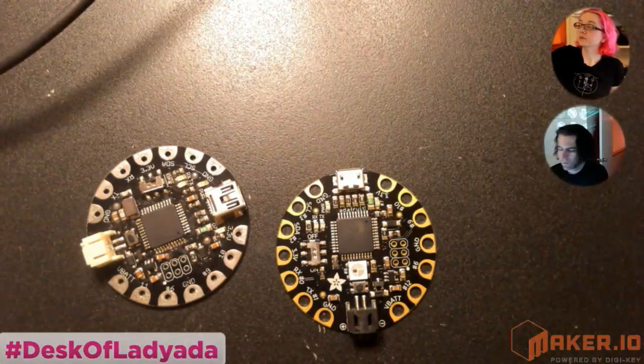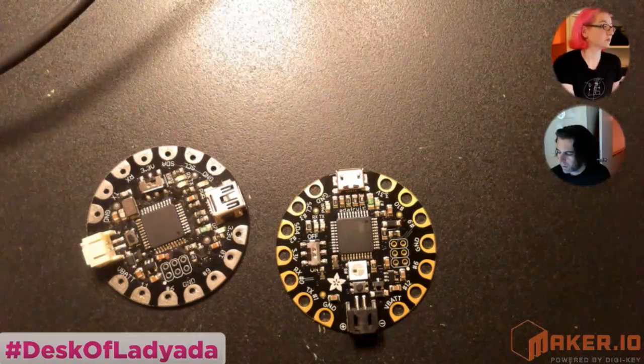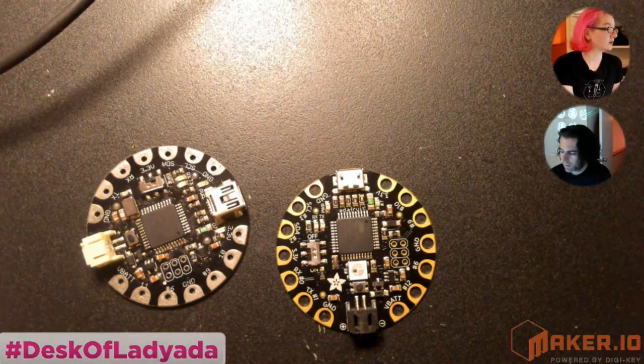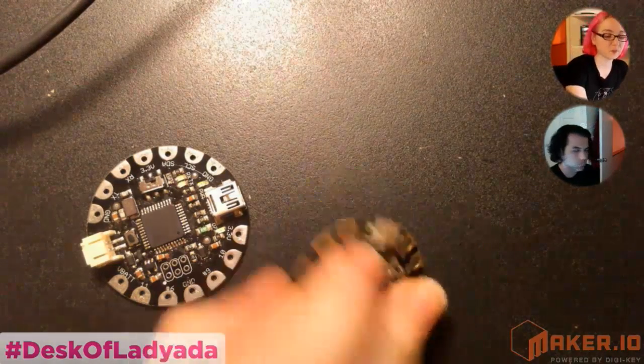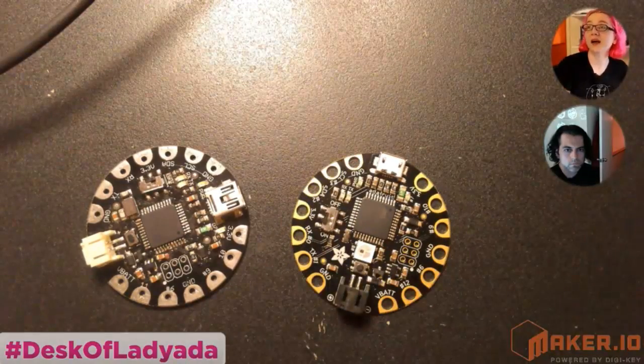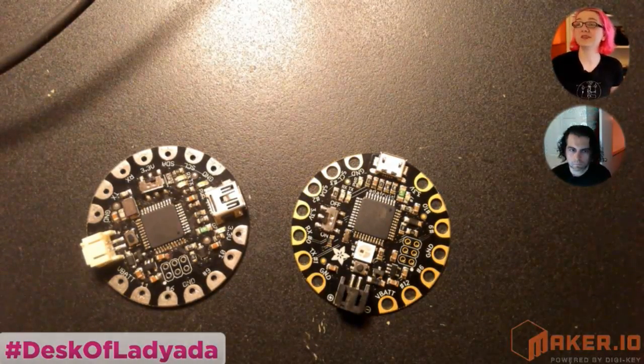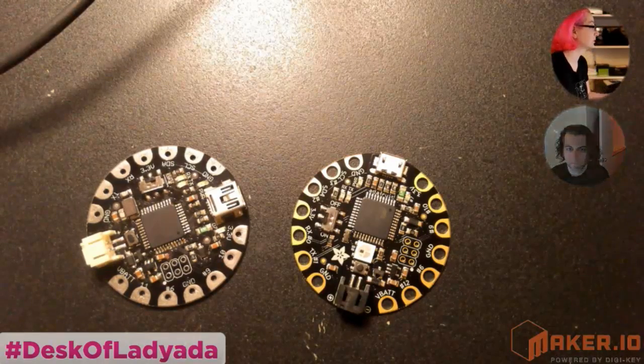Another question, from the chats. Adafruit micro USBs seem to be sturdier than other ones on other electronics. I'm summarizing. Why is that? You have to pick the right package. So this is part of experience. I know that if you want to use a micro USB, you want one that's 50/50 SMT and through hole, which we'll look up.